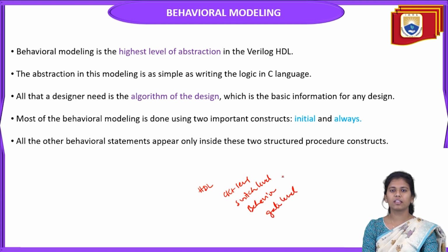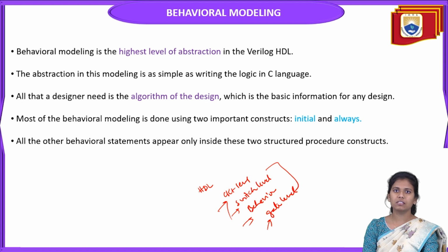Okay, so it all depends on the designer whether he wants to develop a particular module in terms of switch level, or behavioral level, or circuit level, as well as the gate level. And we already discussed what gate level modeling is. In gate level modeling, the development of a particular digital circuit is made with the help of the gates, all the primitive gates. All the gates are well predefined already in the Verilog library.